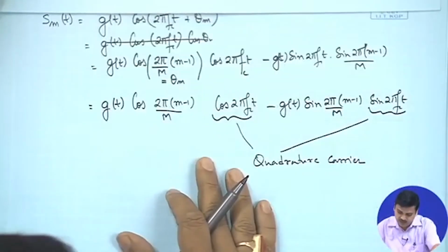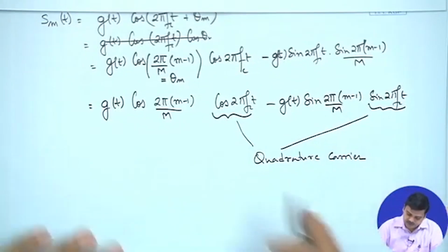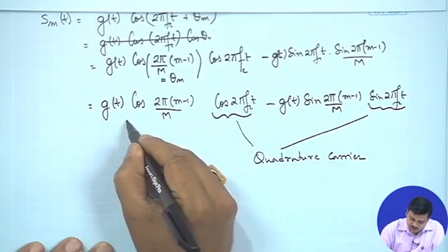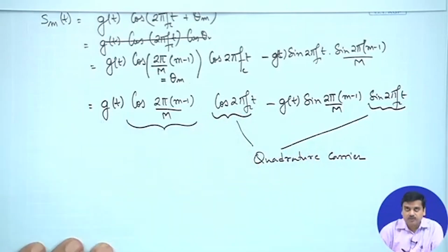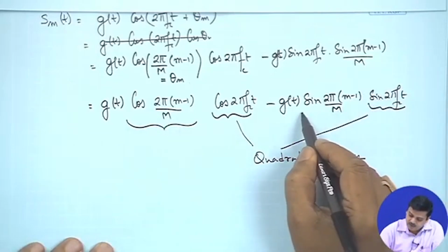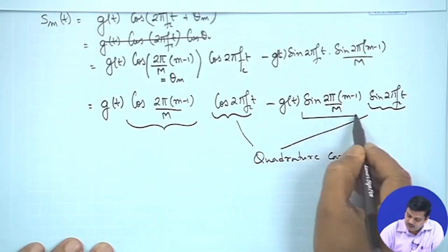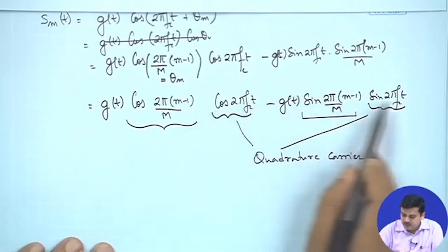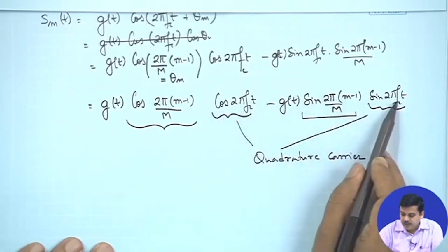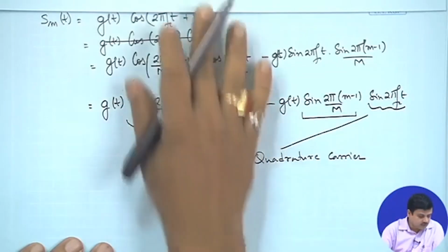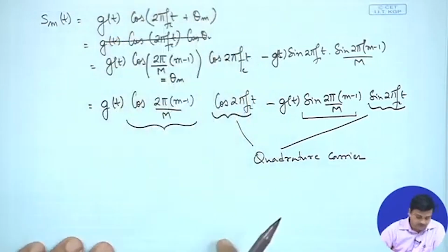Whereas, if we look at this particular representation, we have a carrier and there is some amplitude which is because of the phase. There is another carrier where there is another amplitude being selected, and these two carriers are of the same frequency, but they are at 90 degrees offset with respect to each other, right. So, this is a representation that we can think of.